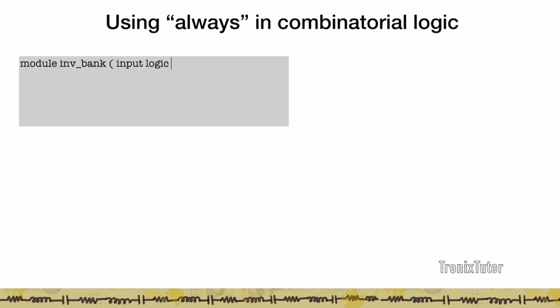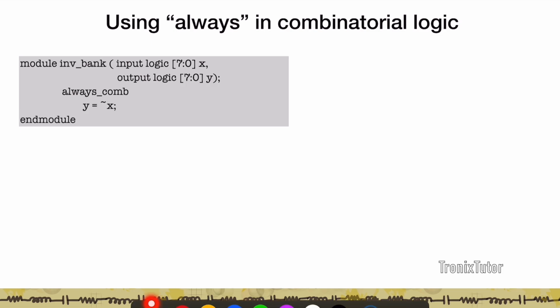Now, this same logic of a latch can be extended to combinatorial logic. So I can use this always statement also for combinatorial logic. Now, one would think, why would you do that? Because you have your assignment statements. For simple logic, generally it doesn't make sense to use always. But always helps a lot, especially when you're doing complicated logic, again for a behavioral case, right? And we look at one example.